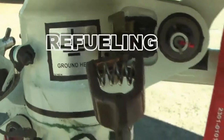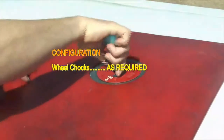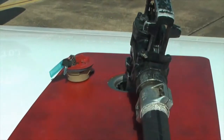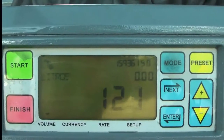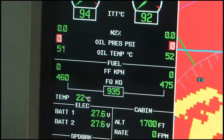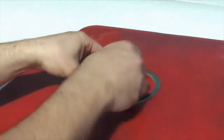Refueling. Make all grounding connections between the fuel source, the airplane, and the fuel nozzle. Open the gravity filler cap and introduce the fueling nozzle into the gravity filler neck. Start the fueling operation and monitor the fuel quantity in the tank by checking the refuel control panel or cockpit indication. After reaching the desired fuel quantity, close the gravity filler cap and remove the grounding cables.